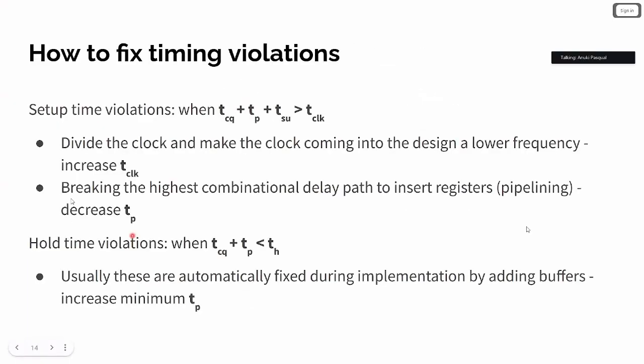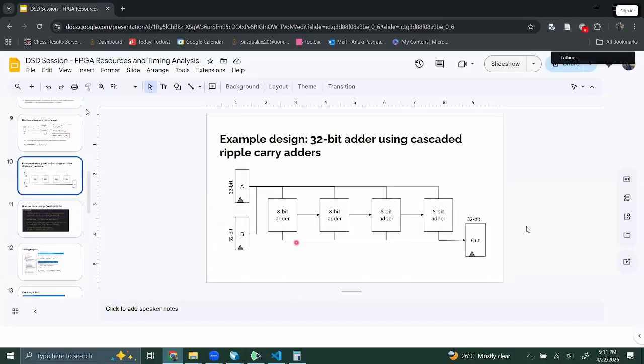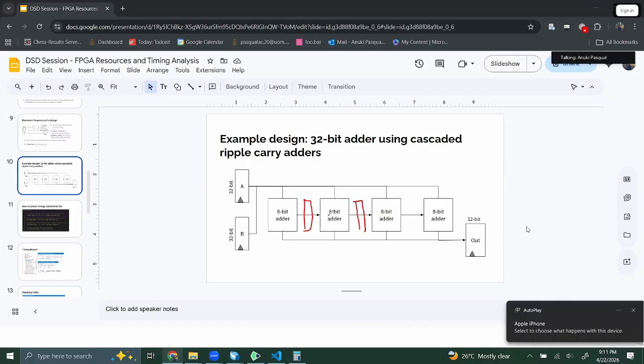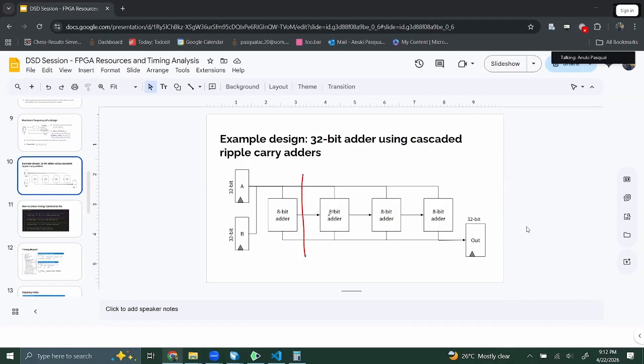And if I explain that with my adder circuit, here, this is the original one, and the improved one is we put registers between these, including all of the signals that are passing between these stages. We put registers. We are sort of saving intermediate outputs and using them in the next cycle instead of using everything in the same cycle.